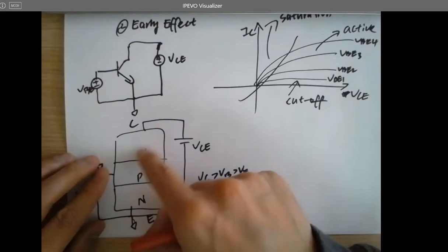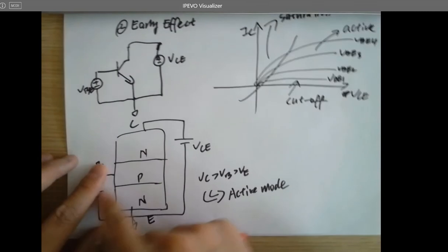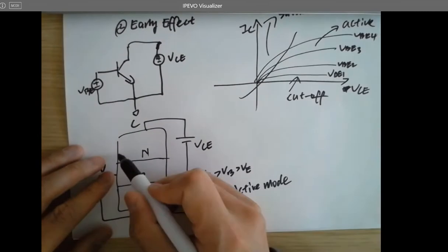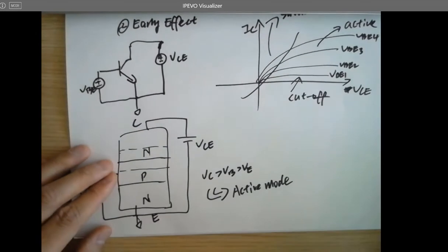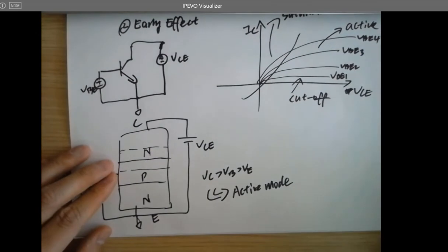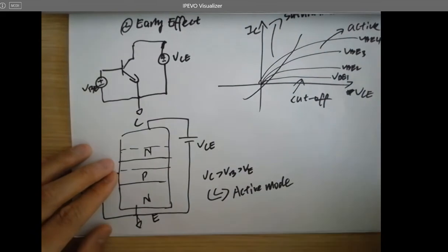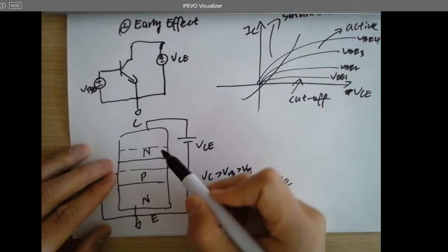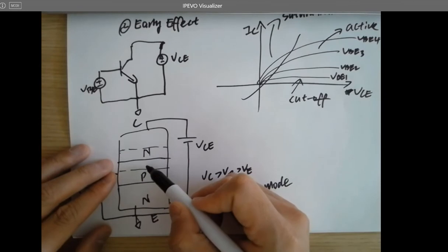So if you have this guy reverse biased, then before you turn on this guy, what's happening? Is there a depletion region? It should have a depletion region, no matter what, right? There will be a depletion region because of the concentration gradient. It can be narrower, can be wider, but there will be a depletion region. And which side has more holes? Which side has more electrons?